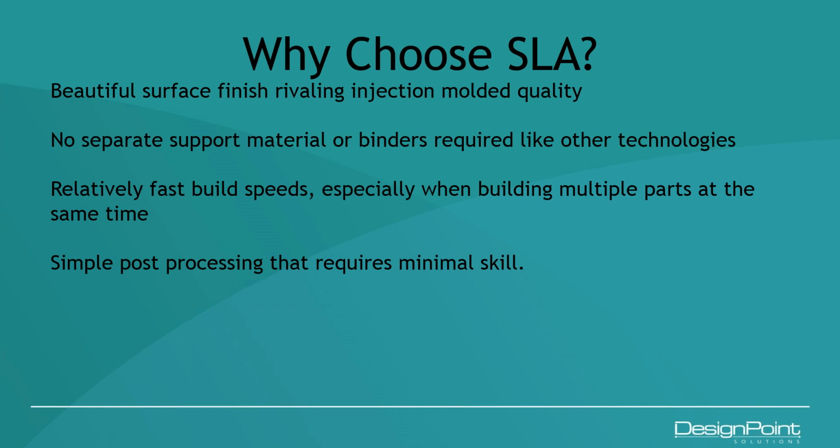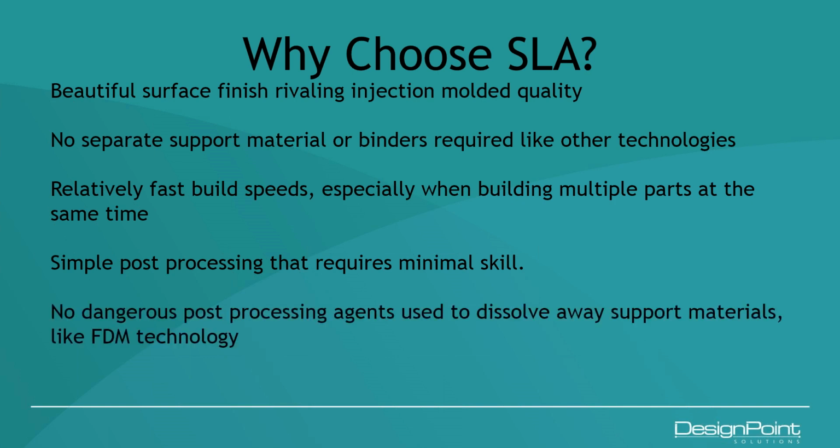Excuse me, post-processing that goes on, and the good news about SLA is if you compare it against a number of other technologies, it is very straightforward and takes minutes to take care of instead of hours like some technologies. FDM, for example, has a relatively lengthy support cleaning process where you're either breaking parts off by hand or using mechanical tools, or dropping it into a sodium hydroxide bath to dissolve off this support material. That can take as little as a couple hours and potentially as long as 12 to 14 hours from what I understand. There's also no dangerous post-processing agents used to dissolve away the supports.